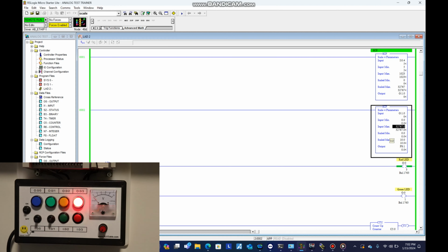And we're going to scale that from 0 to 10 because we have 10 volts here. So when we go halfway between 0 and 32,000, like 16,000-ish, as you can see on the screen, that puts us pretty much at 4.95, and some change. So that's actually going to be half of it. That's 5 volts. If we max it out, we are going to max it out right down here at 10. And as you see, as I turn, this value changes.